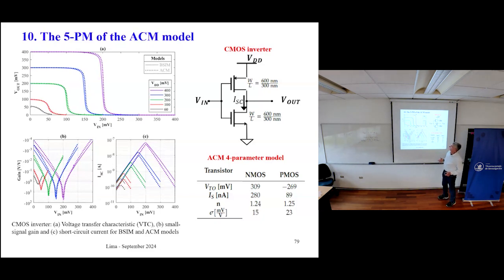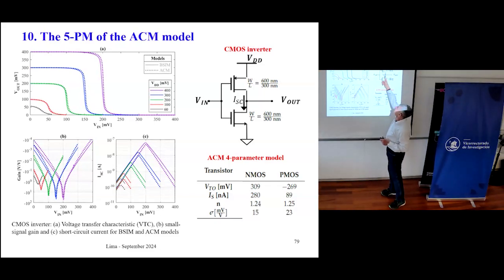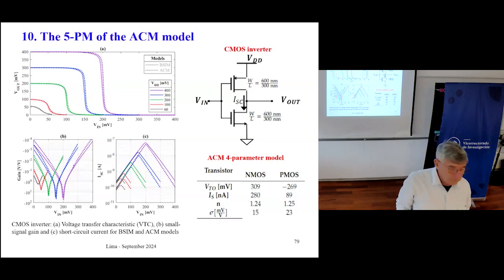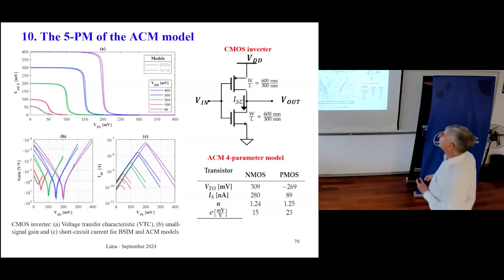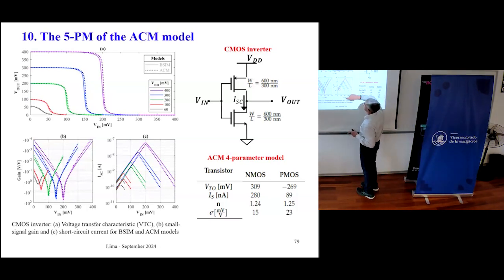This is not an ideal circuit. Even when the voltage here is 0, this transistor has some leakage. If VGS is 0, is the current 0? No, the current is not 0. You have some current. If VGS increases, this voltage increases, you have some increase in the current.